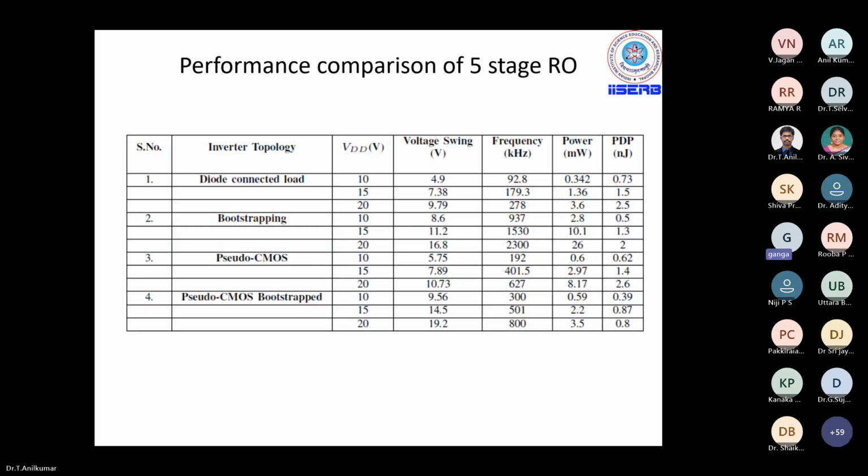So what we have done, we characterized these gates at different power supply voltages. And also we have designed a 5-stage ring oscillator with all these gates, and we were analyzing its performance. We know that a ring oscillator is nothing but an odd number of inverters connected in the fashion of a ring.